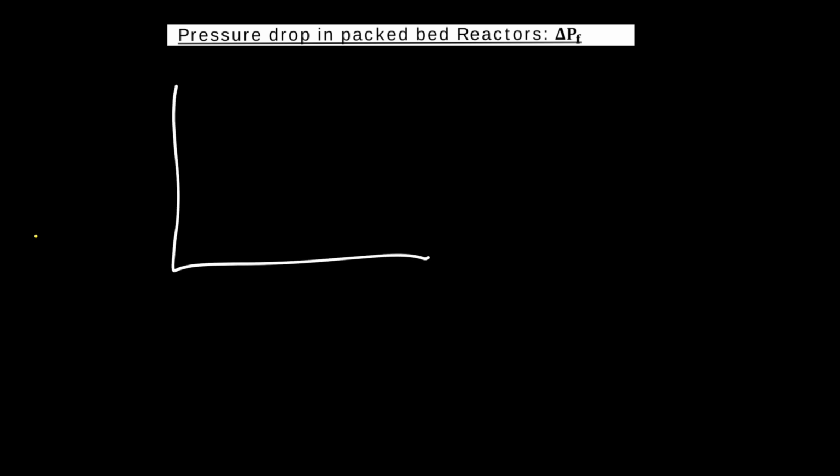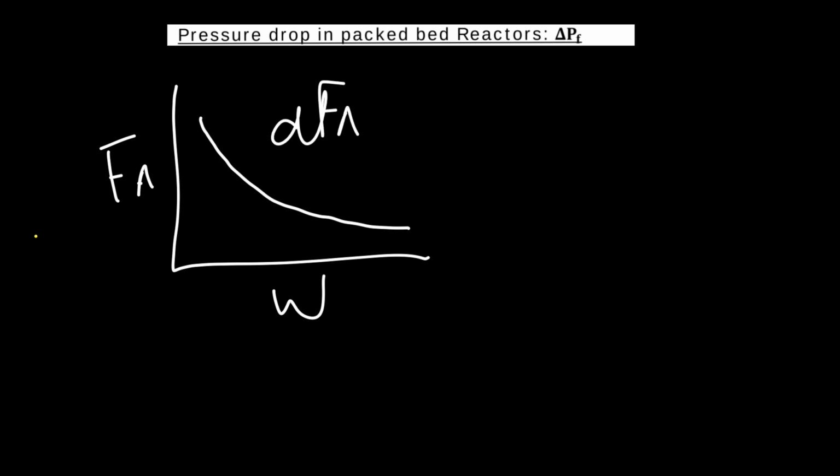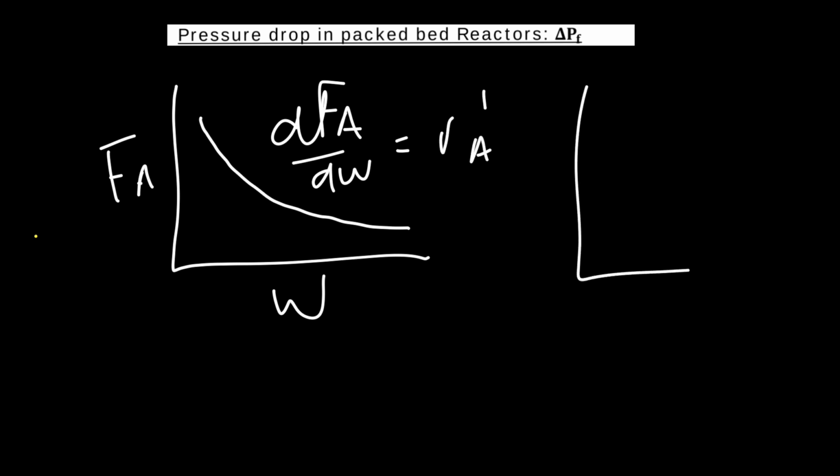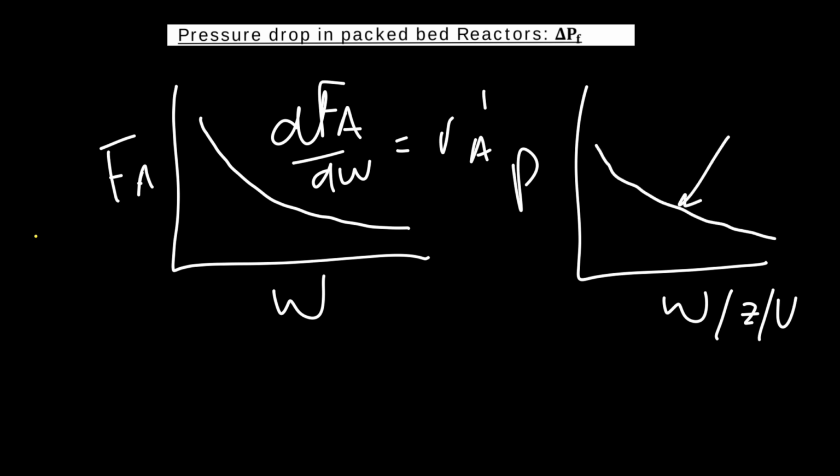So of course, in CKN, you were able to construct curves of how the molar flow rate will change along the length of the reactor, because we had our mole balance for the plug flow reactor that we could simply implement. So now what we also need is an equation that says how does the pressure change with either mass or length or volume of my reactor. So we need the equation that describes the slope of this line as I move along the length of my reactor, so that I can integrate that and calculate the pressure at any point to plug into my rate equation.